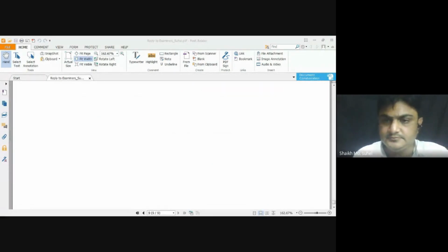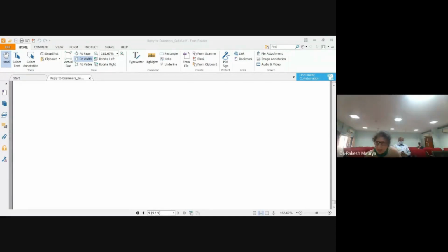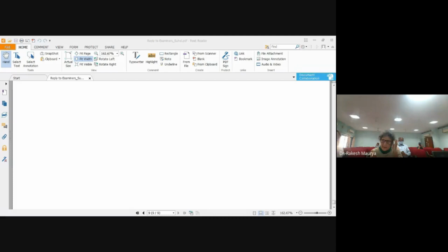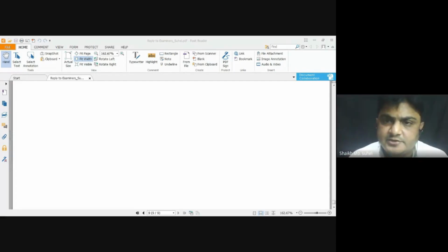Okay, thank you. Welcome. I will ask you a few simple questions in general, not specific to your work, just a few questions on your work. Because you have worked on PWM, can you tell me what is the frequency of the zero sequence component so far as a six-phase induction motor is concerned? Sir, in the three-phase or six-phase case, zero sequence frequencies are multiples of three, so that is 150 hertz.